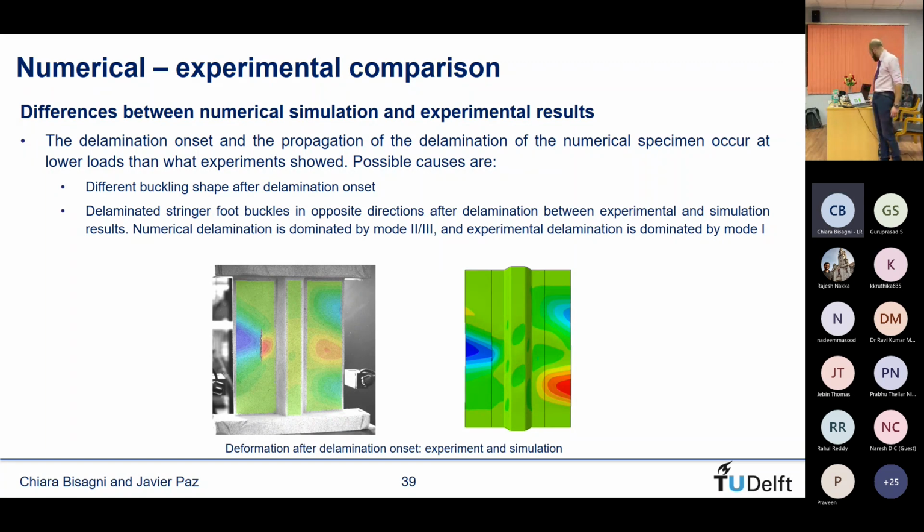When you talk about the post-displacement, have you assessed the impact of that on the local deformation mode? Not on the post-displacement itself, but because the boundary conditions will be different, since you have a finite stiffness compared to probably what you have in the FEA now. Have you accounted for that in the simulation? No, but that is extremely important. We have seen that in industry. It's extremely important to tailor the boundary stiffness. And we have seen very different results, especially in the out-of-plane deformation direction.